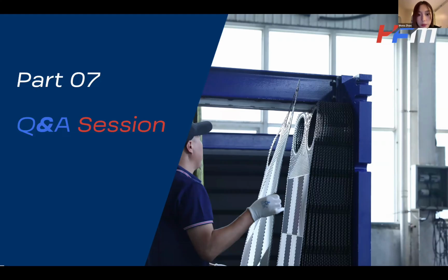So we do see Mary ask, what are common mistakes to avoid when using a plate exchanger in sugar or ethanol production? Vital, could you answer this for us? Yeah, it's a great question. I think most of the damage could be avoided by regular cleaning, proper gasket selection, and maintenance schedules, which are particularly critical in sugar or ethanol production processing.